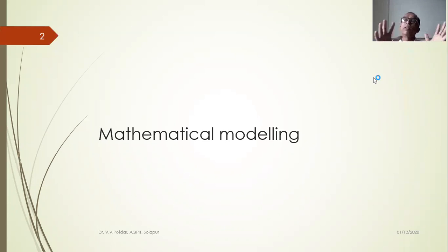Now, once I know that Bernoulli's equation or the energy equation can be used, I'll be able to prepare a mathematical equation of operation for this carburetor. For these inlet conditions of this much air flow rate and this much fuel flow rate, if I apply this much suction pressure, I'll be getting this much air-fuel ratio. So these input-output conditions I can supply to this equation of operation, which is based on the energy equation, which is based on Bernoulli's concept. And then I'll be able to solve this equation for the output mixture strength.